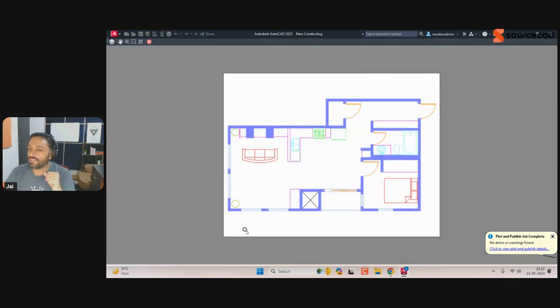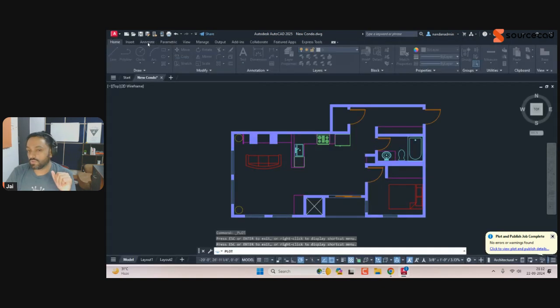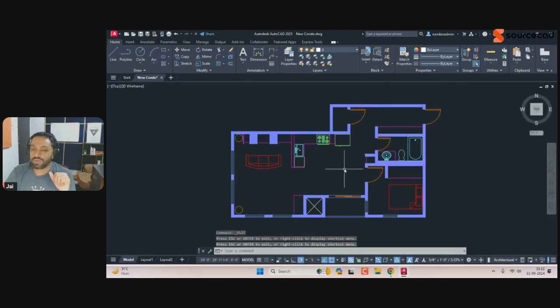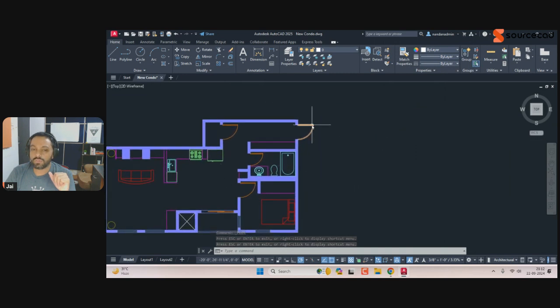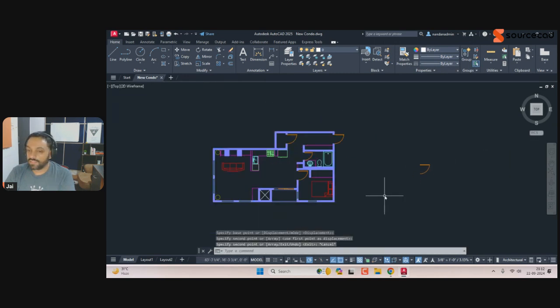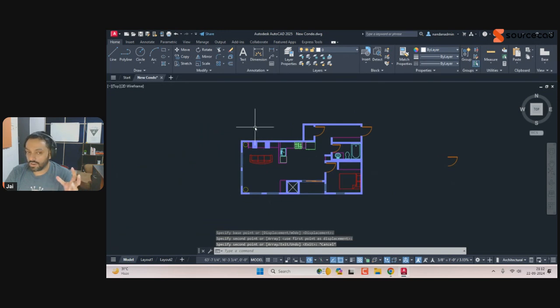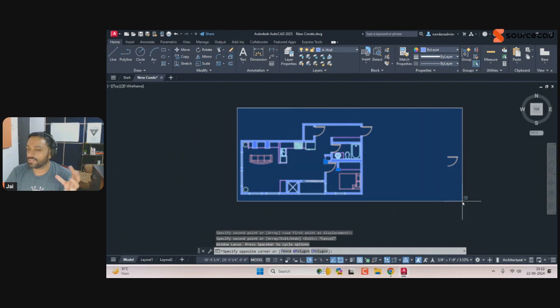So the drawing will look like this. As you can see, it now fits nicely in this sheet of paper. It just removed all the white space. So extents is really going to work well for this drawing. But what if we have something like this? So we have part of this drawing here, and let's for a moment assume that we also have something maybe here. Now, in this case, if you select extents, AutoCAD will include this entire box, this thing.